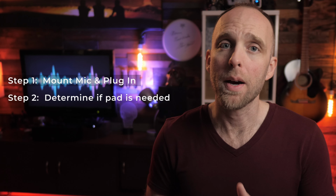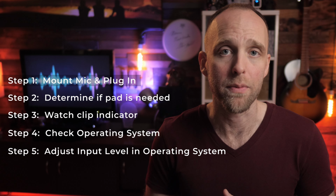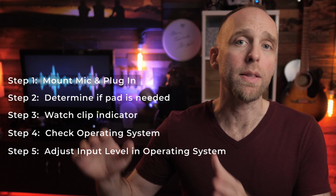All right, so finally, let's get a good signal into our computer. Let's set our gain for our signal flow and for what we're trying to capture, which is our main sound source, in this case, my voice. Then we'll watch the clip indicator on the mic to determine if we need to use the pad. Then we'll check the system preferences in Mac or Windows sound settings, and then we'll check our software or our meeting platform. Always start at the sound source and work towards the destination. Never start at the destination and work your way backwards.